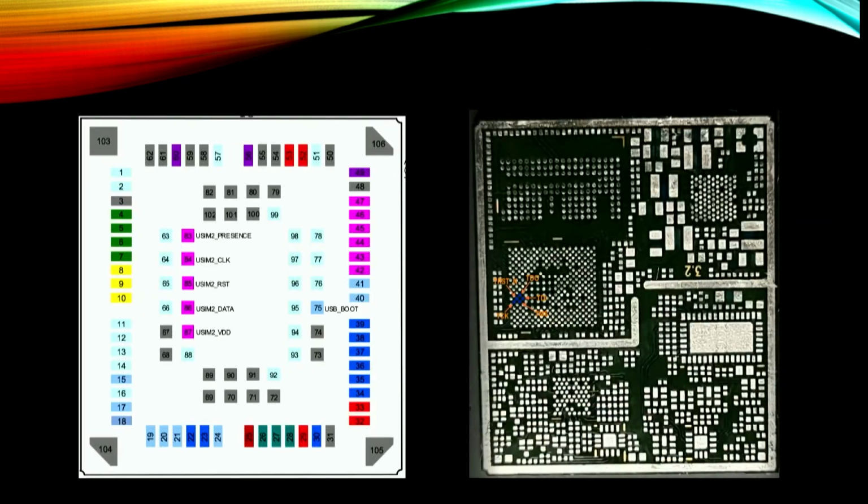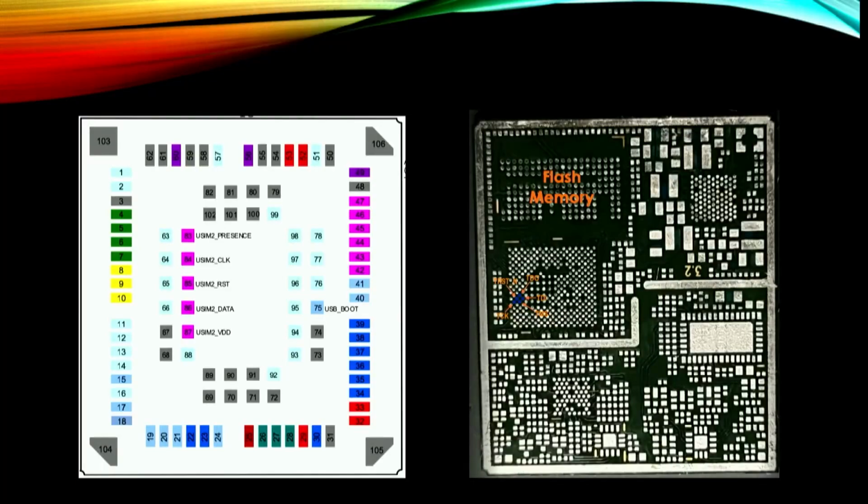That is a land grid array, which I think is the EG91. We start looking at the layout up here after it was cleaned. That's where the flash memory sits, and that is a BGA multi-chip package, which we're going to get into a little deeper here. The other part is the actual CPU. I'm always curious, can I get JTAG on there? It's not always easily available on these devices.